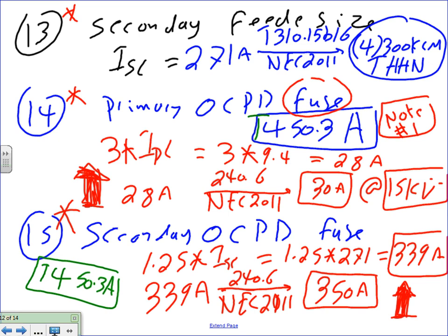Almost there. Any question, guys, about this? Can anybody tell me what's the voltage of this fuse? 350? What's the voltage of this fuse? Huh? 600. The voltage of this fuse, 600. I didn't write the voltage next to it because if you're low voltage, most likely you're 600 or 300. In this case, we're 480, so we're 600. This one, typically you write the voltage next to it because it's higher than 600. Any question?